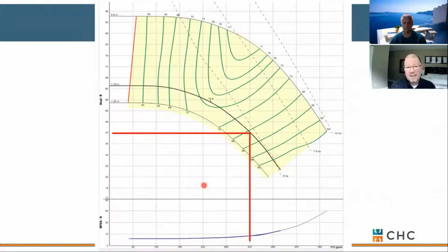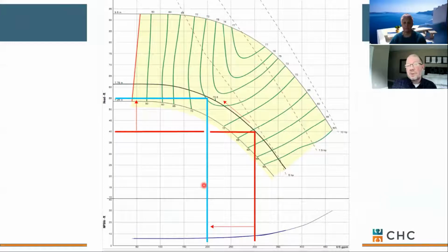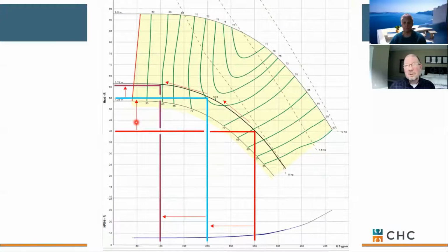When you do that, you back up on the pump curve, and as a result you see an increase in pressure. In this case, we've increased pressure by about 6.5 pounds. Now we can pick up that increase in pressure and slow our pump down. There's energy savings there. We close another two-way valve, and guess what? Our pressure continues to climb, and same thing, we slow our pump down accordingly.